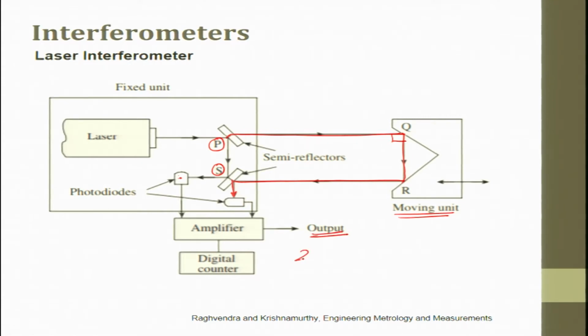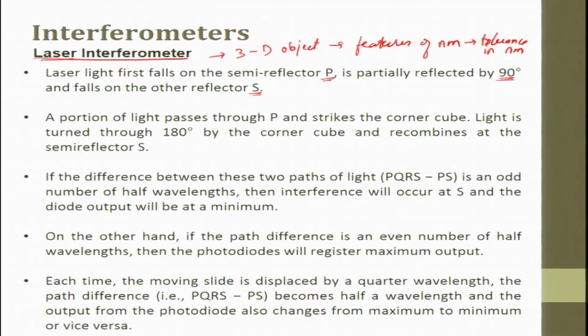So, basically what you get is a 2D line plot, then you stretch, join several of these 2D plots, you get a 3D on a surface. With this you can try to measure on a surface using laser interferometer techniques. And by the way, very far off distances can be measured. For example, you have a very large table. Today we talk about table size, bed size of 10 meters. So, we use laser interferometric techniques to find out the variation all along the flat.